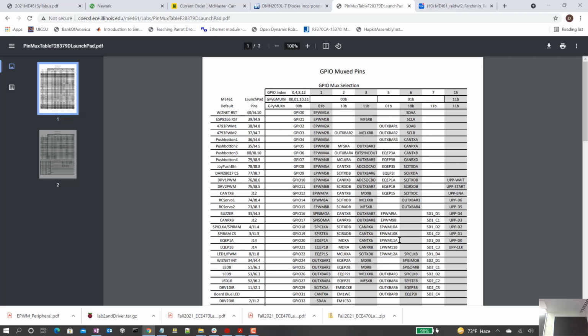Okay, but for example here, let's look at it. So our pin GPIO. Let's see where's one for LEDs. So for example, LED 8 is GPIO 25 here. That just happened to be what I chose, by thinking about all what I wanted to do with the board. But not only can it be GPIO 25, we can also change the mux such that it's this out X bar. This has something to do with signaling, so don't worry about that.